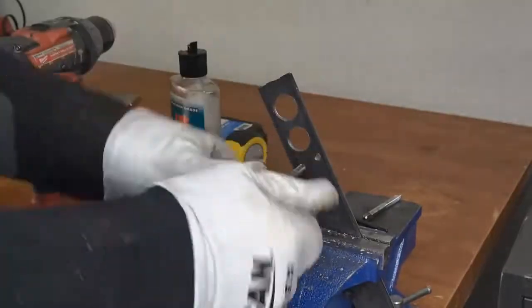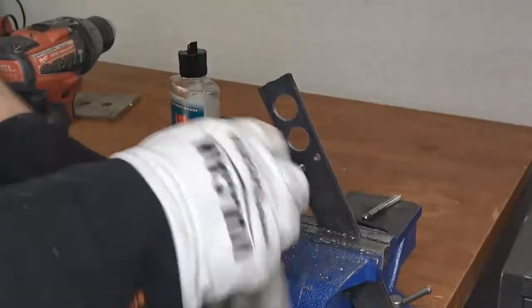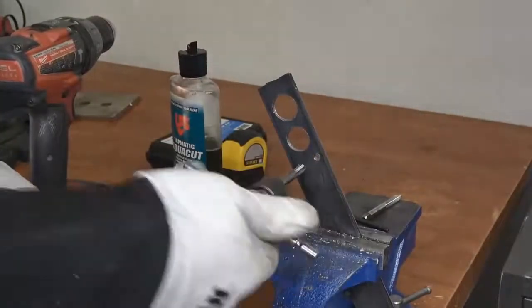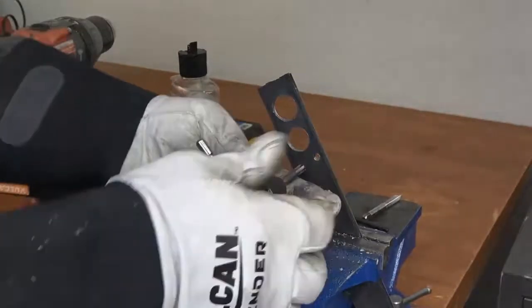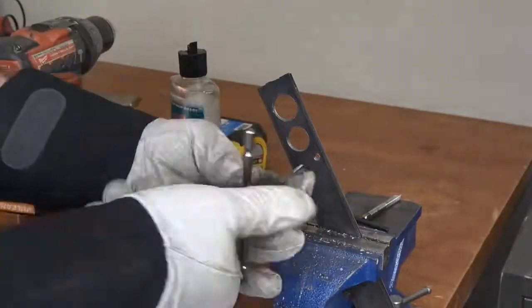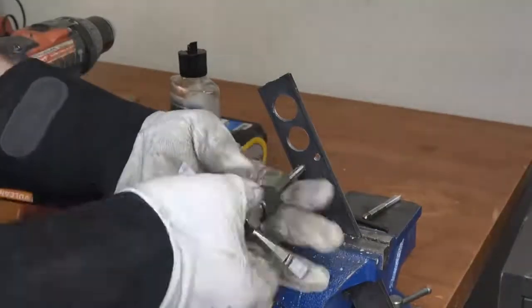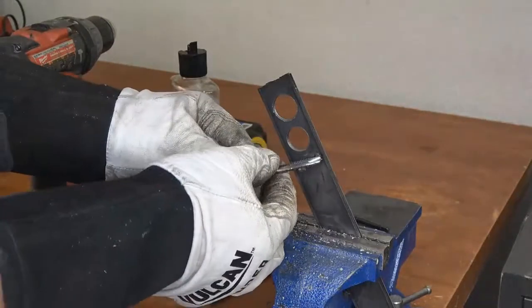You could see how if you were using this type of taper tap and you had to install a continuous hinge that had 40 screws, this would take you a long time. It just cuts down on the efficiency of the installation. And yes, you could do it, but this is why a lot of technicians will substitute screws, because they don't want to tap like that.